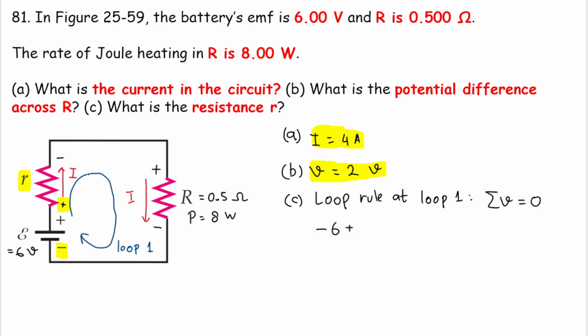For getting the voltage, I can multiply the current by the resistance, so I will have R multiplied by I. And then plus, again, we have this resistor here, and the loop is entering from the positive terminal, so we have a positive sign. And we have 0.5 ohm here, but that is resistance. We need to multiply it by the current, and all of that will equal 0.